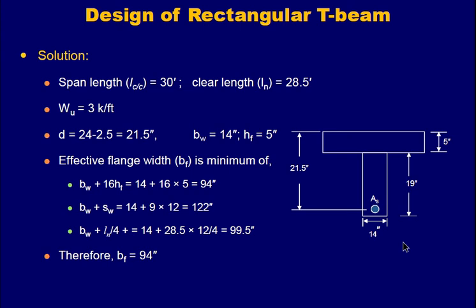You have to plot this data in the figure for better understanding. Okay, so you had 24 inches of total depth and 5 inches of slab, so this 24 inches of complete depth minus 5 inches, so you are left with the 19 inches. Okay, and this is the depth of the steel, effective depth of steel, tension steel.